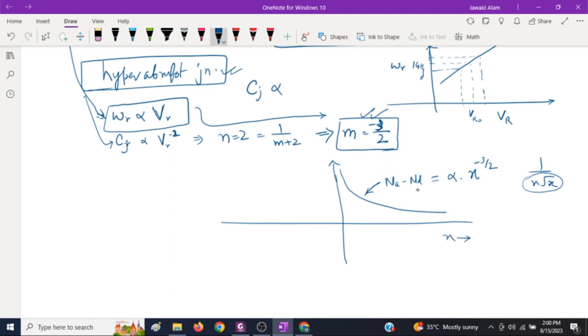If this is the doping profile, practically it is not achieved exactly like this, but generally there is a very high concentration at the middle of the junction at x equal to 0, and then it decreases. Instead of increasing the doping concentration, it decreases. It has the highest dose here. Practically you cannot achieve this because ultimately this line will cross 0 somewhere over here, and the line will look like this.